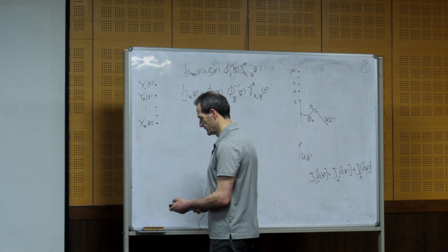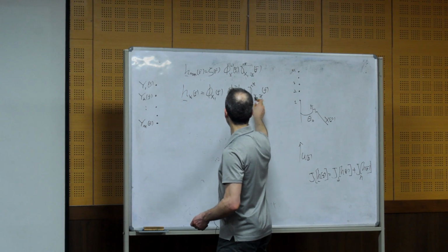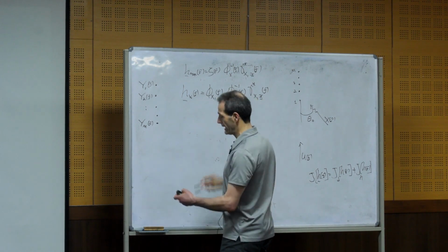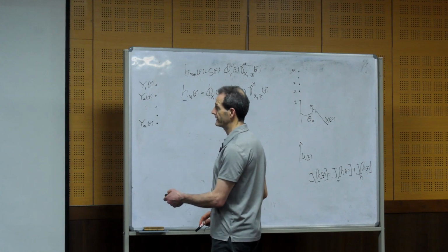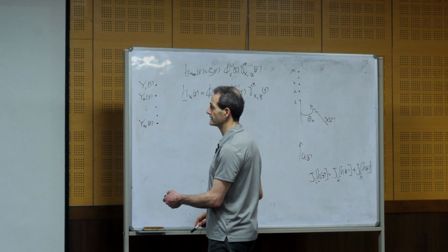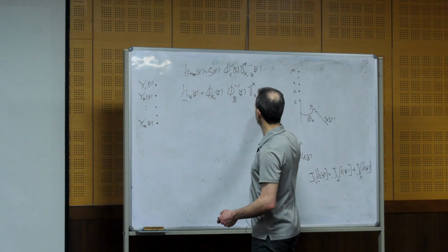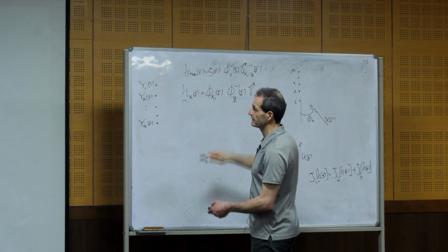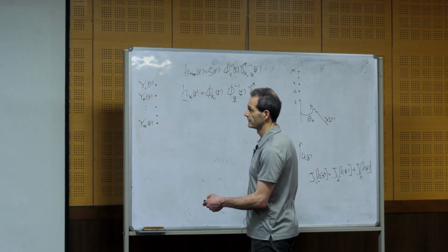This is the partially normalized coherence function, so I can write it like this. I can write the Wiener filter by the coherence without the normalization, because phi x1 multiplied with this partially normalized function is simply the coherence between the vector x and x1 complex conjugate.